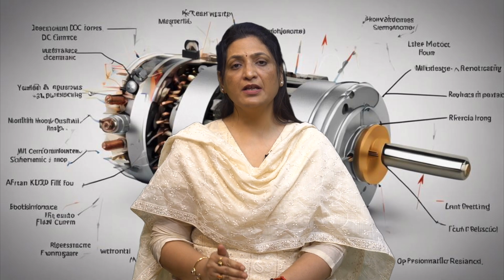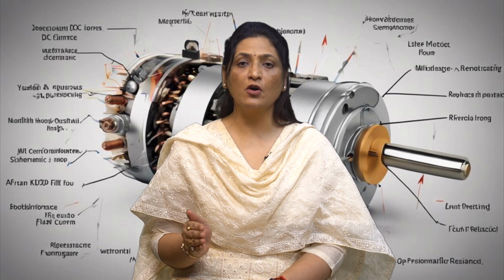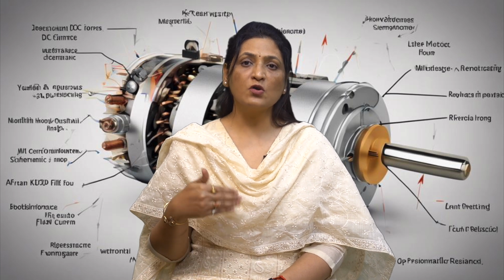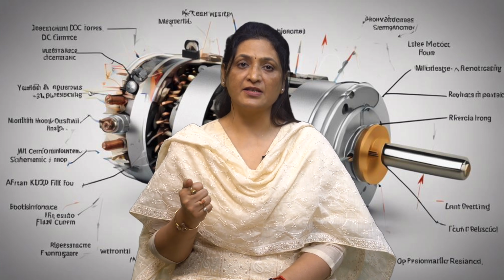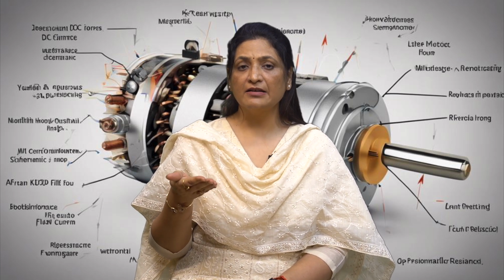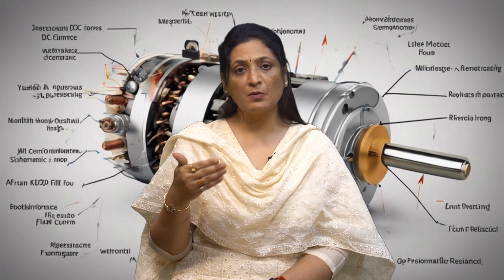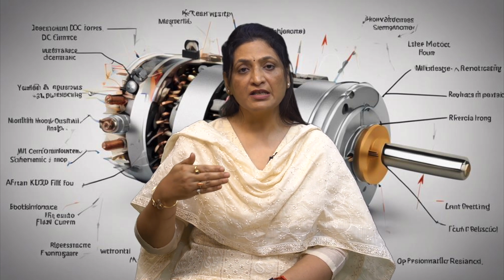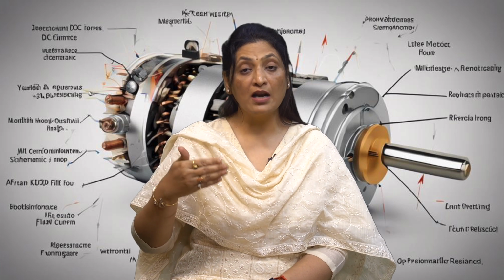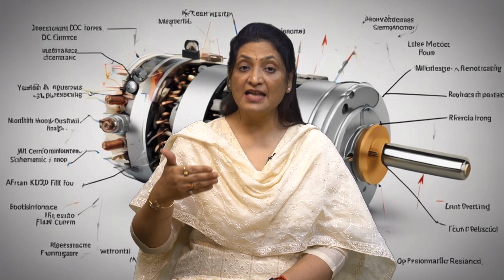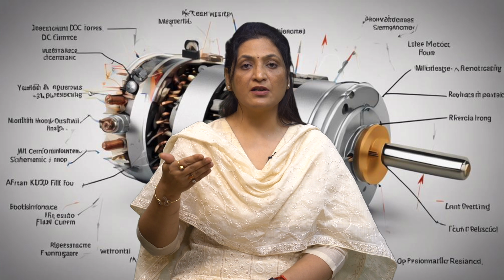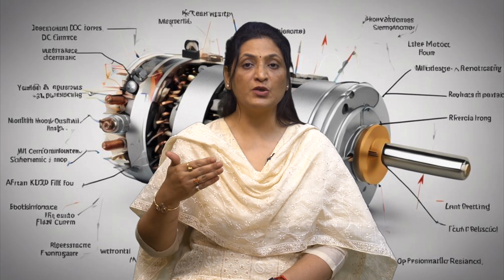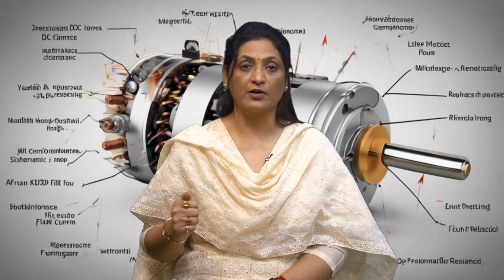The difference between the armature torque and the shaft torque is the loss torque, which is also shown in the characteristic. So, at start, the armature torque is proportional to the square of armature current. So, the motors can produce high torque for small amount of armature current. Hence, the DC series motors are suitable for the applications which demand high starting torque.